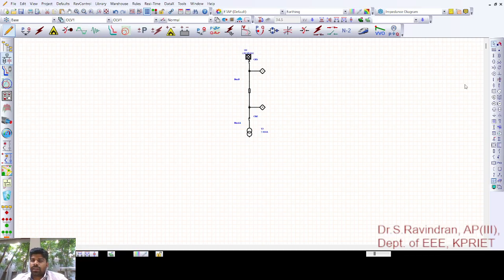so now it is set, it is a 230 by 415, 3 MVA transformer. Now again from the transformer I need to feed the feeders. If multiple feeders are there, then I should take a bus. Okay, now if I connect the bus, it will take 415 volt. Before that, to ensure my protection, I am again giving a circuit breaker with relay systems and everything for the protection of this transformer.